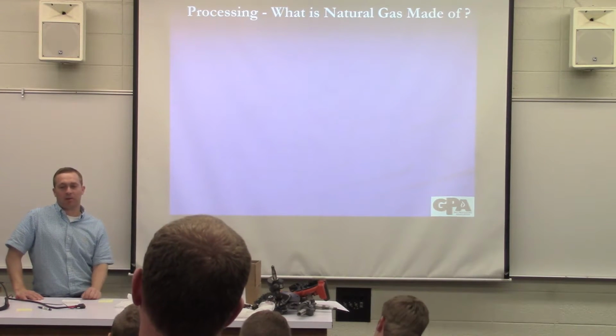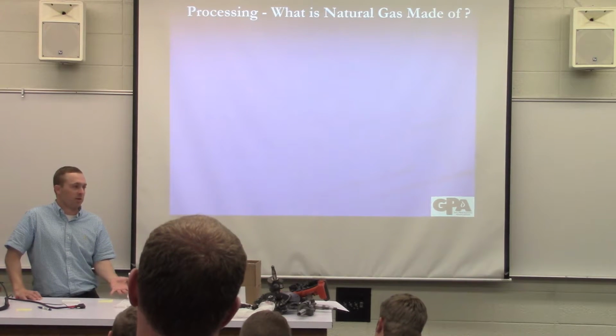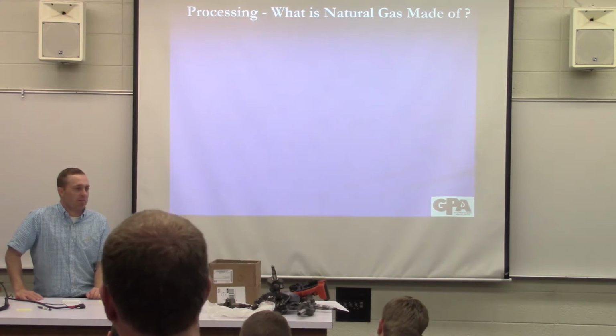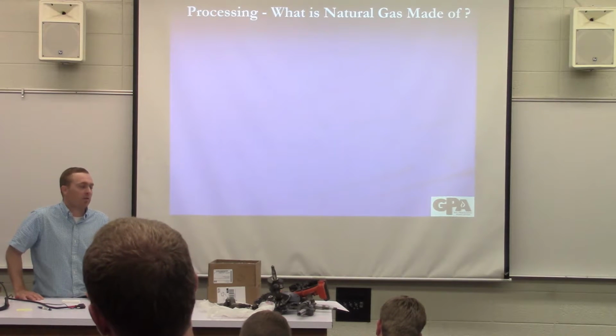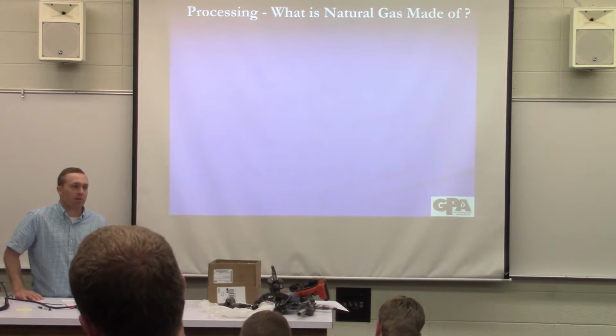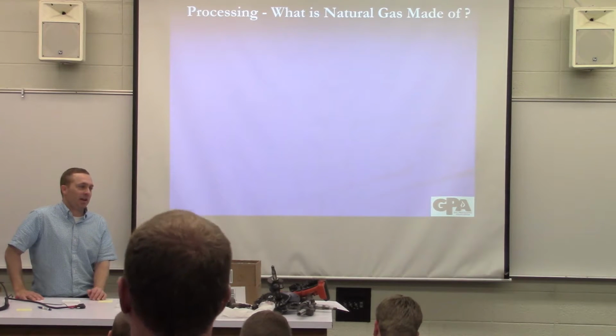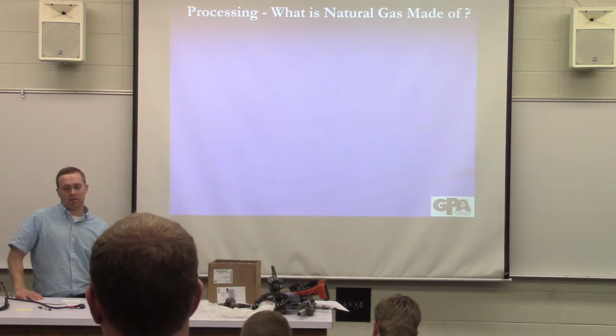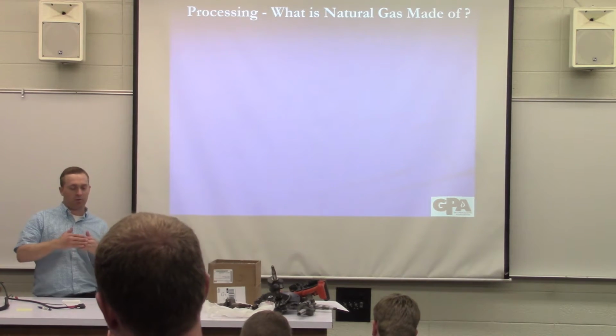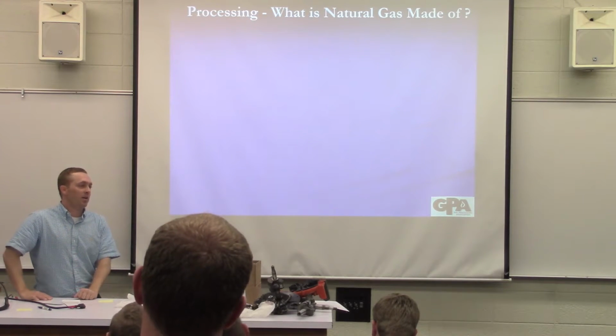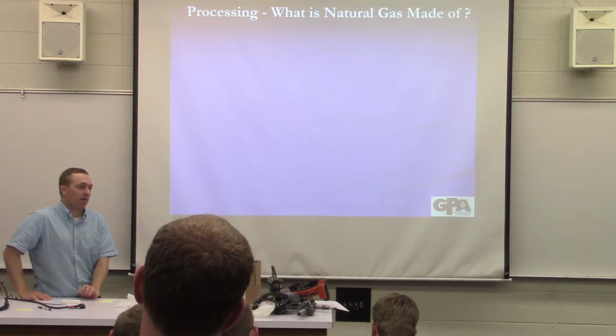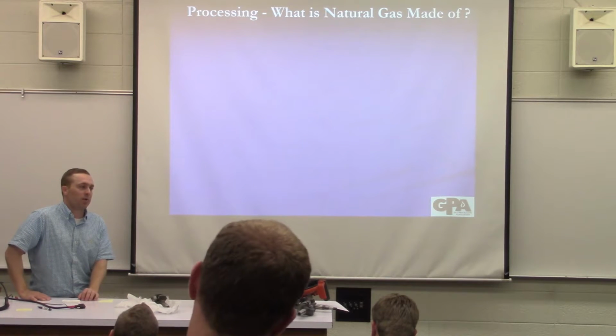And Dr. Baxter, you might be able to give a better answer than me, but simply it's freezing, right? So the way we process natural gas to recover these components is we get it really cold, and so we'll sort of push up against the point where we're going to freeze the carbon dioxide in our cryogenic processing facilities,